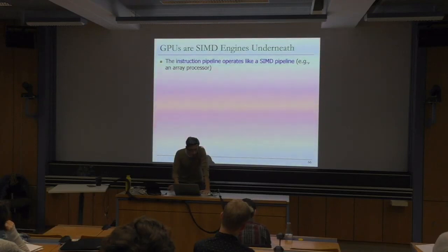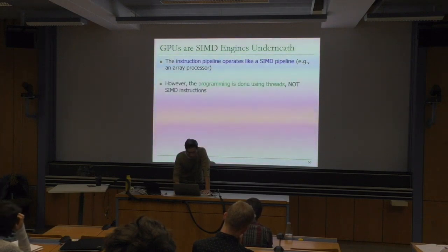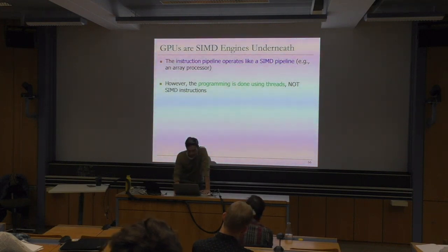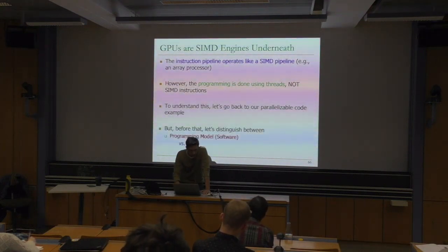They are SIMD engines underneath. That's the first thing to take into account. They are a combination of vector and array processors. But they are special in the sense that they are not programmed in the traditional SIMD programming way with these vector instructions and so on. They are programmed using threads, such that we can write code for each of these threads individually. But for sure, it doesn't make sense to have very different programs for each of these threads. We will likely have the same program for all of them.